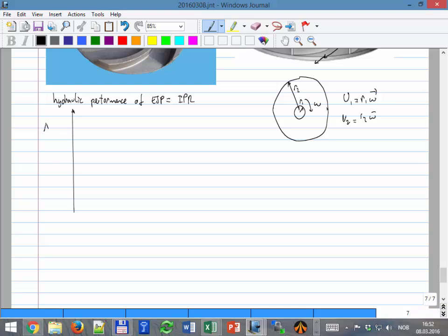It is the delta P across the pump versus the rate, and actually this rate is the actual liquid rate. So that's a big difference. This is not available pressure, but this is delta P across the pump, and this is the actual liquid rate at pump inlet. How does it look if it's similar to the IPR? Like that.